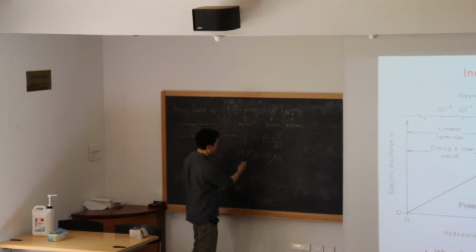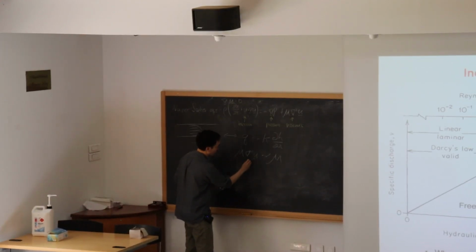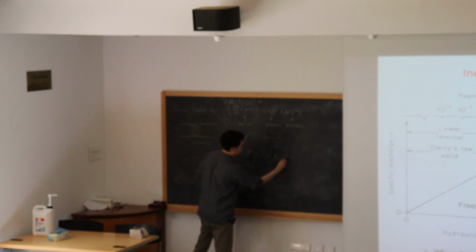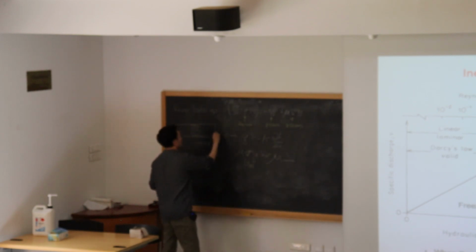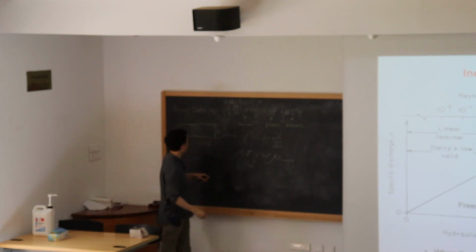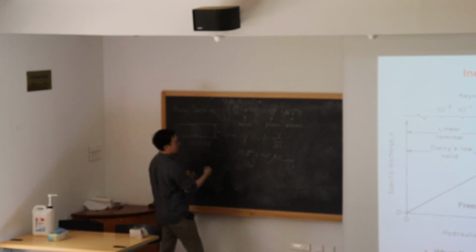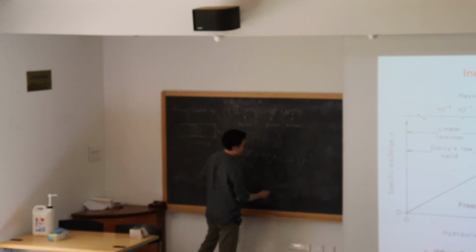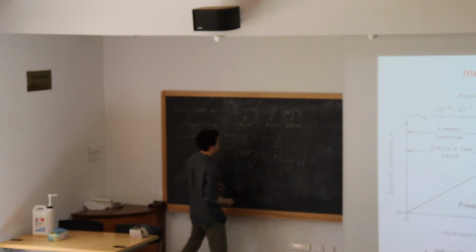Exactly. So what we can use as a length scale, since this del square is 1 over delta x squared, here what you use is simply 1 over b square. And you can use the average velocity; you can take the average of this velocity and you get u. So that's mu times u over b square.